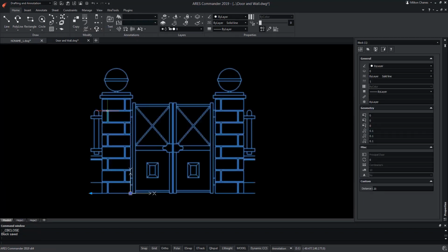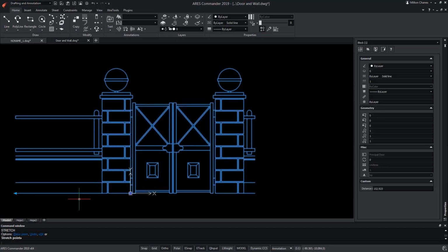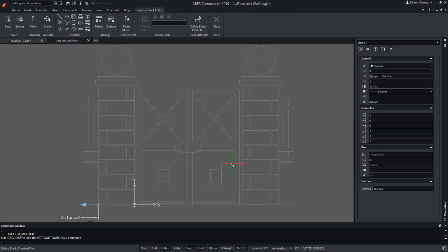We select the block, and we see that the grip appears where to stretch it. With this, we can verify that we've controlled the first part of this fence. However, we're interested in the fact that the vertical frames of the fence are copied as we stretch from the grip. Therefore, we edit the block again by double clicking on it.